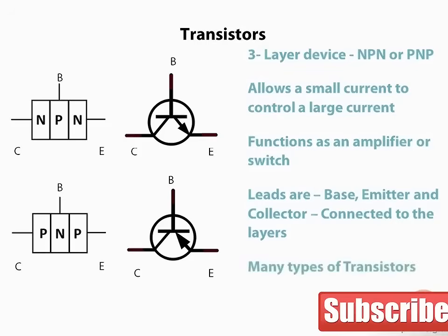There are many types of transistors. What is common to all transistors is that they all have 3 leads and perform the same function, controlling larger currents with smaller ones. The properties and application can be somewhat different between each type. Different types of transistors include field effect transistors, or FETs, metal oxide semiconductor FETs, or MOSFETs for short, JFETs, and unijunction transistors, to name a few. We're going to focus our study on the very humble bipolar transistor.